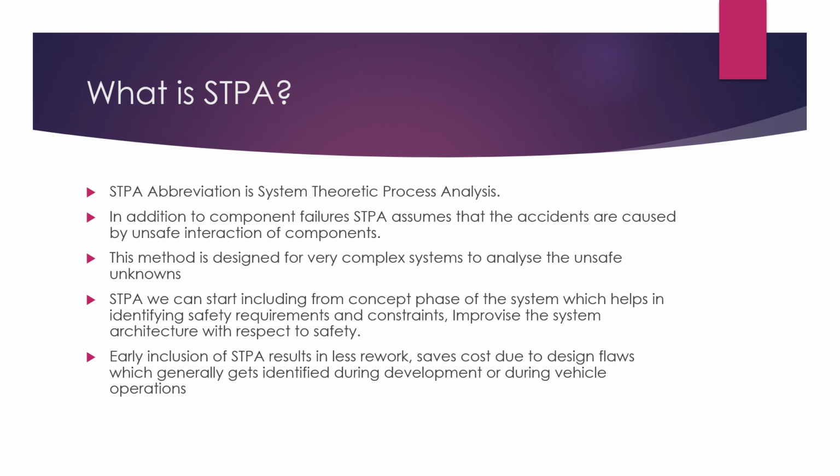STPA we can start including from the concept phase of the system, which helps in identifying safety requirements and constraints, and improving the system architecture with respect to safety. Early inclusion of STPA results in less rework, and saves cost due to design flaws which generally get identified during development or during vehicle operations.